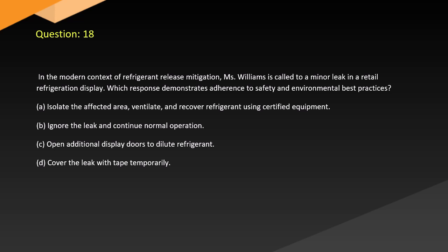Question 18. In a modern context of refrigerant release mitigation, Williams is called to a minor leak in a retail refrigeration display. Which response demonstrates adherence to safety and environmental best practices? A. Isolate the affected area, ventilate, and recover refrigerant using certified equipment. B. Ignore the leak and continue normal operation. C. Open additional display doors to dilute refrigerant. D. Cover the leak with tape temporarily.